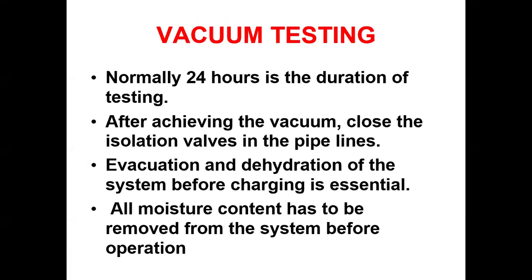Okay, that's it. Next, it's about the vacuum test. Nitrogen will go inside the evaporator and condenser also. These are especially preferred for VRF projects. So a VRF project consists of a lot of pipelines, isn't it? That means the primary piping distance should be comparatively high. So at this time, we don't know where the leaks will be, isn't it?